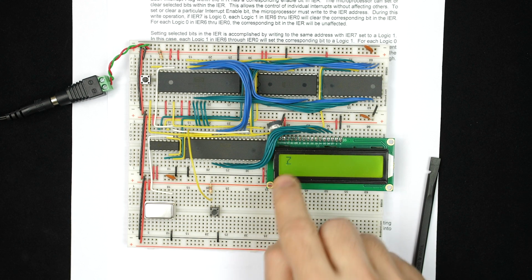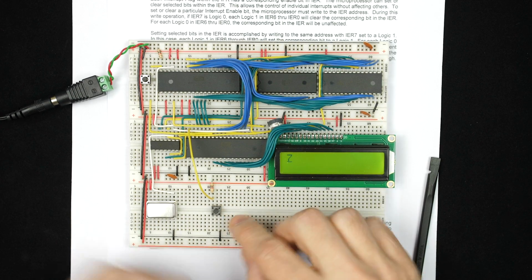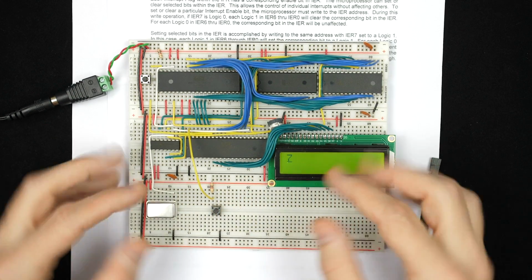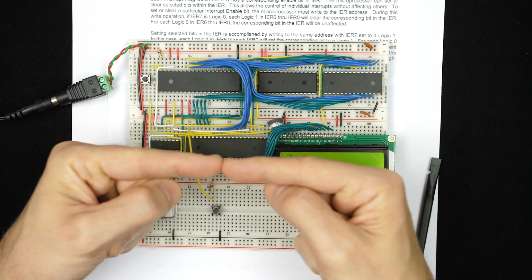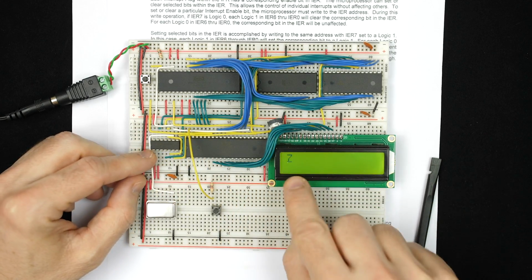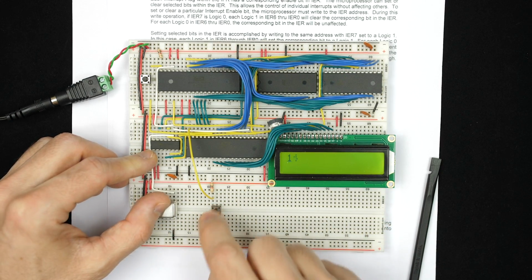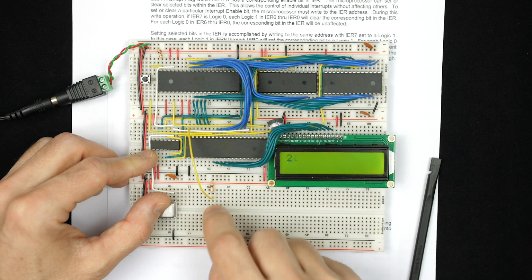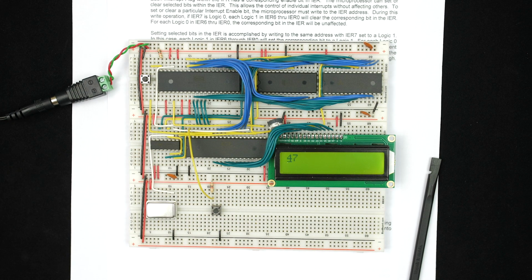Well, we got a few, but I think that we got a few because the switch is bouncing, right? Because there's no debouncing circuit in here. So when I push the switch, the contacts might bounce, and each little bounce is going to cause a negative going edge, and it's going to count every one of them. So if I'm careful, I can have it count by ones, but every now and then I get a few extra counts in there. And there's actually a few solutions to that.